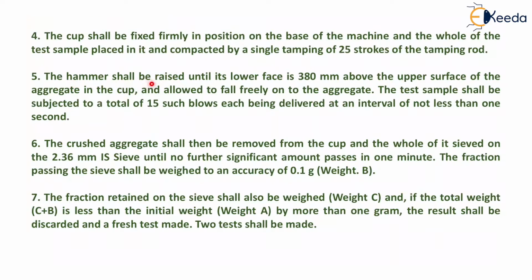The hammer shall be raised until its lower face is 380 mm above the upper surface of the aggregate in the cup and allowed to fall freely onto the aggregate. The test sample shall be subjected to a total of 15 such blows, each being delivered at an interval of not less than 1 second.